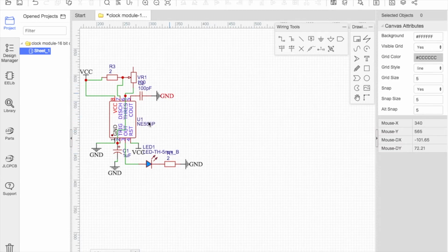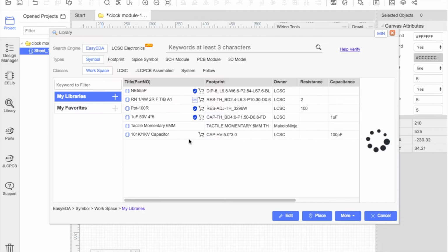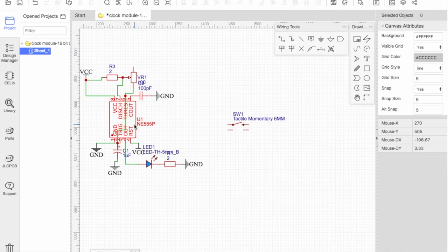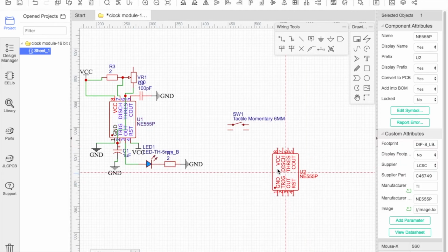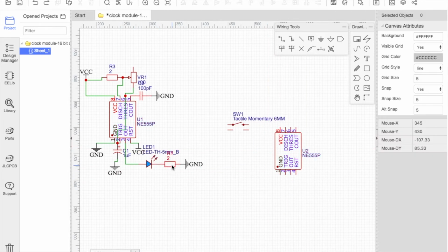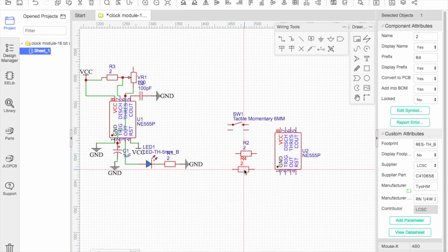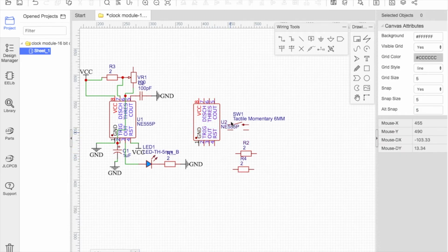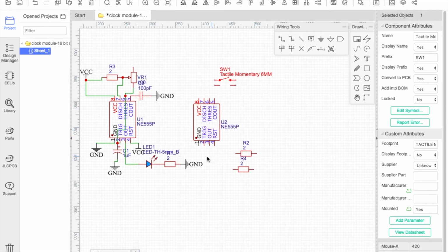So now I'm going to build this circuit on Easy EDA. So I got basically everything I need already here from the astable circuit I built last time, so I can just duplicate a lot of stuff here except for the button. So I place that down. I'll duplicate the 555 timer, and I'm gonna need a couple of resistors, so I got them out. I'll put the 555 timer in a good spot. Move that out of the way.